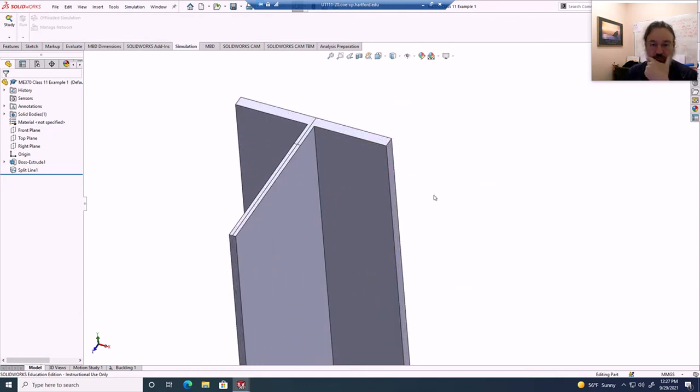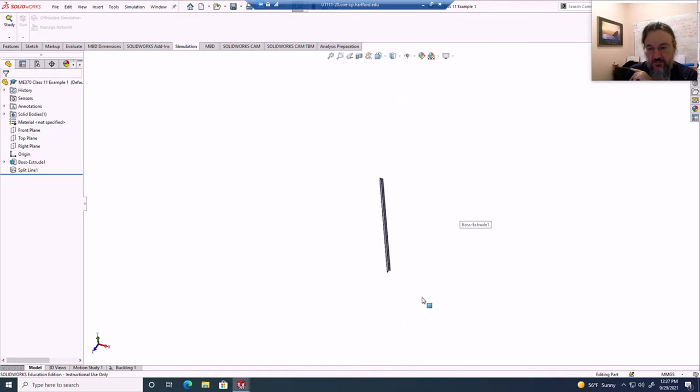And I'm in SolidWorks. I've made these little lines right here so that I could grab hold of a spot to try to simulate a pin-to-pin connection. It would actually be kind of difficult along the x-axis to do it, but I did it along the y-axis, both at the top and the bottom of here. But you can see how long and slender this thing is with the proportions they gave us.